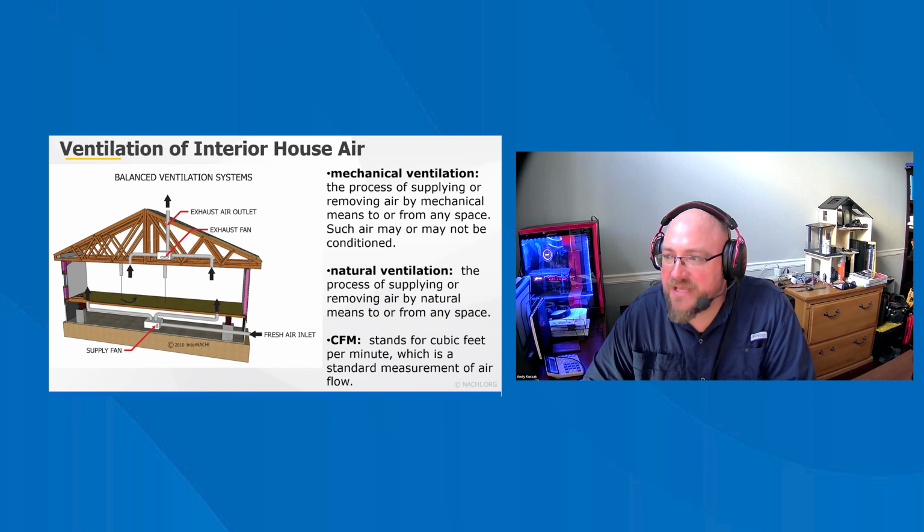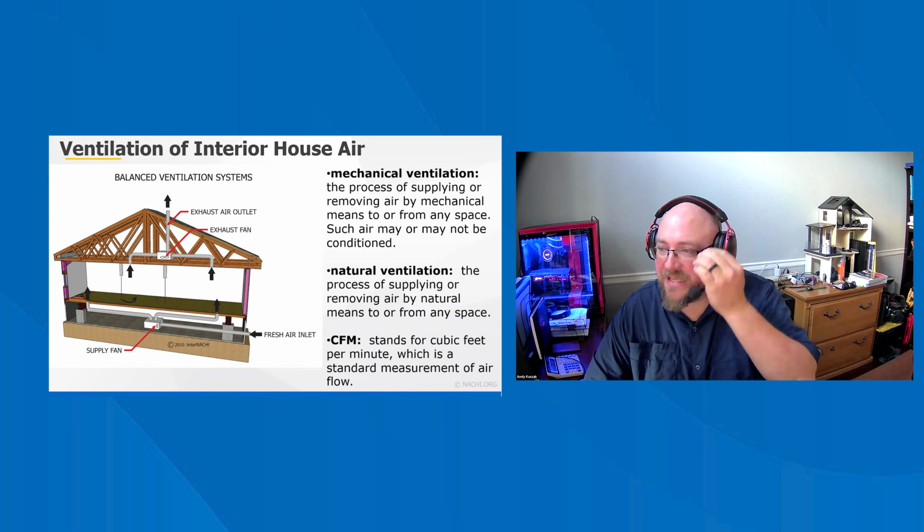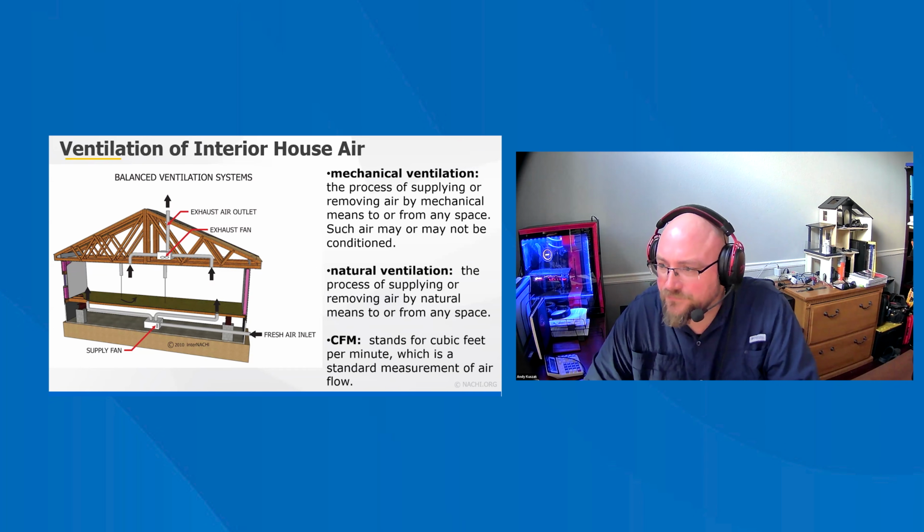Automatic or gravity dampers that close when the system is not operating should be installed at the exterior air hoods, intake, and exhaust.